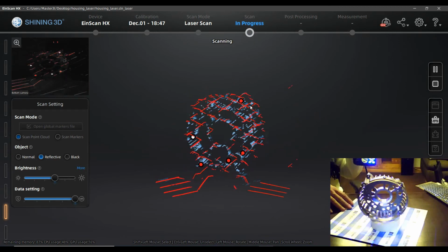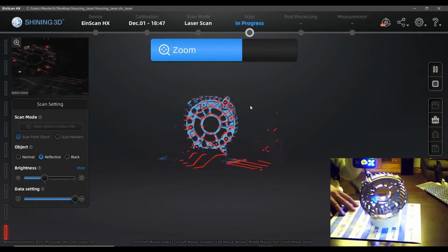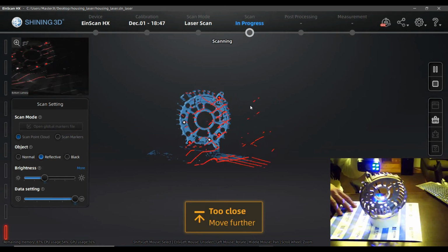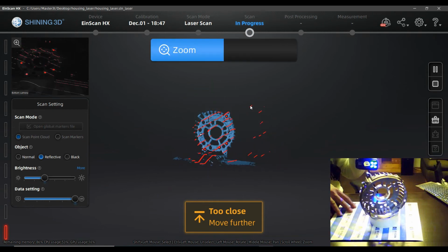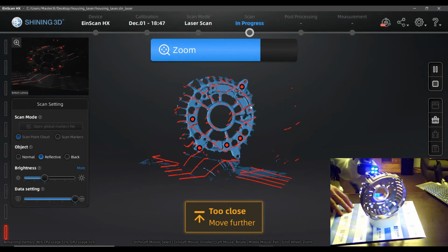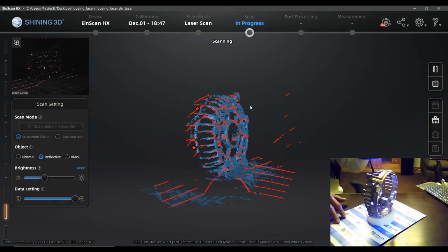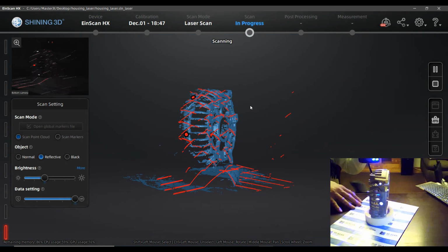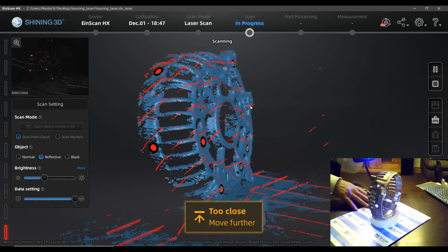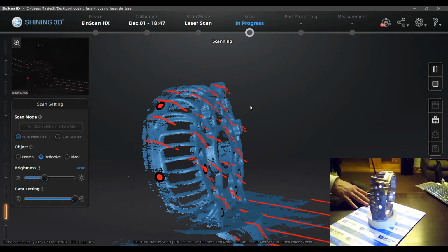As you already learned, you can play around with the brightness. And yes, I zoomed already, so I'm going to show that again: there are up and down buttons that zoom the view you are scanning in and out. It's not a zoom of the scanner itself, so be aware of this. It's just a zoom of the view in the center, what you are seeing inside your monitor. So you are not influencing the result of the scan like this.